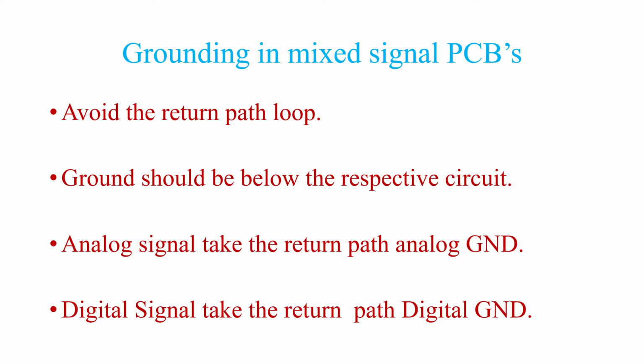Some of the basic thumb rules have to be followed by the PCB designer or the high-speed PCB designer while designing mixed signal PCBs. Avoid the ground path loop, and he has to take care of the routing of the return path, and he has to carefully check while routing the signals or after completion of the routing.